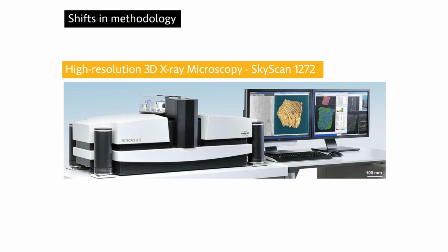Quantification of the textural phenomena of fine-grained ceramics is complicated, as small voids and particles require high resolution. Because the scanned sample needs to be rotated close to the Röntgen source to achieve high resolution, usually the size of the ceramic shard has to be reduced to meet the required parameters, and thus the analysis becomes destructive. We attempt to use micro-CT for fine-grained materials, which were used for most of the wheel-made pottery during the late Iron Age in Central Europe. Thus the resolution of the CT scan is crucial for us.